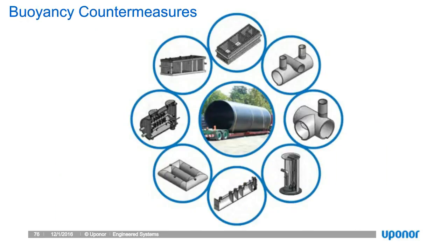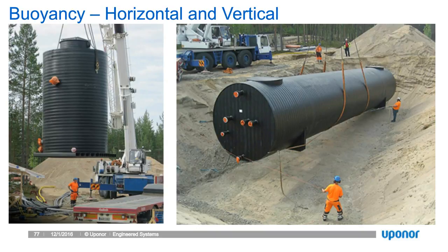So one question that comes up frequently is, okay, so Wheelite and Wheelite modular systems are 1/10 the weight of concrete. How do you counteract buoyancy? Is buoyancy a concern? And the answer to that is it's fairly simple. We design all of our systems assuming a submerged condition, where the vessel is fully submerged in the field. That's the most conservative approach, but we find that it gives us a sense of calm in the face of uncertain groundwater table information. Typically, we have seasonal high groundwater issues, and it's often hard to pin down the groundwater table. So we find that it's best to approach the design assuming a fully submerged condition.